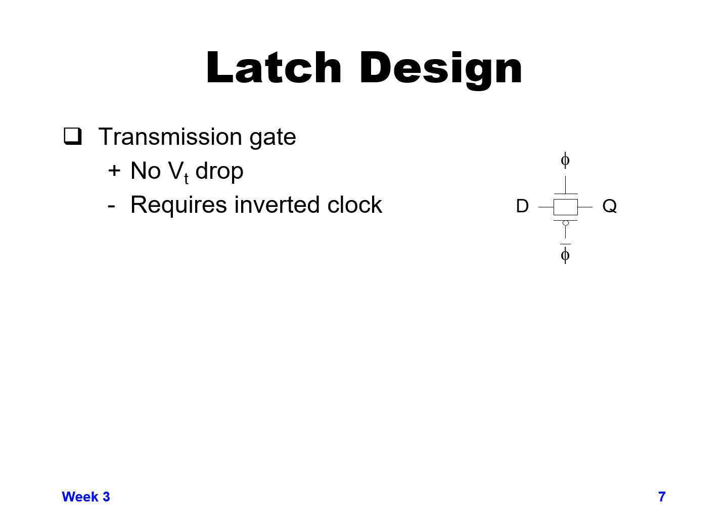compared to the previous one that we just talked about is it also requires an inverted clock. So you need to invert your clock, and you're going to have more clock load on this than the previous single transistor pass design. But at least you don't get the VT drop through this type of latch design. Again, you still have all the other cons that were listed from the previous foil.